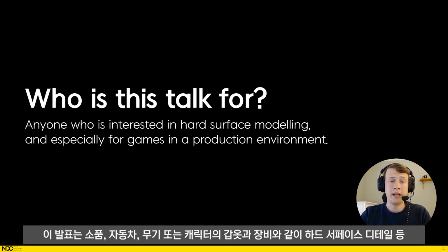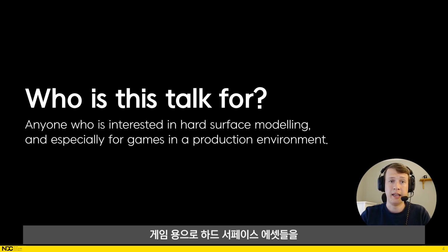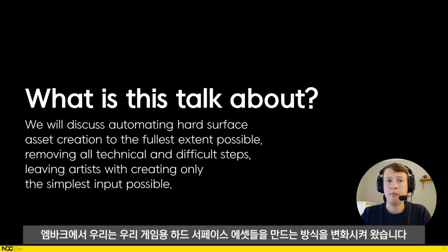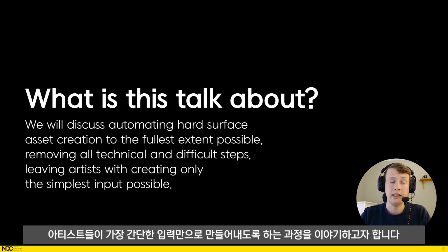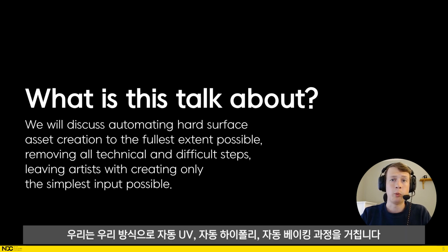This talk is for anyone who is making or is interested in making hard surface assets for games, be it either props, vehicles or weapons, or hard surface details such as armor and gear for characters. At Embark, we have been changing the way we build hard surface assets for our games. In this presentation, I will discuss our process for automating hard surface asset creation, leaving our artists with creating only the simplest input possible. We will go through our take on automatic UVs, automatic high polys, and automatic baking.